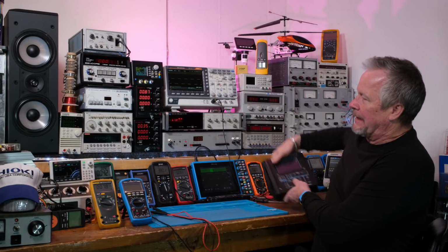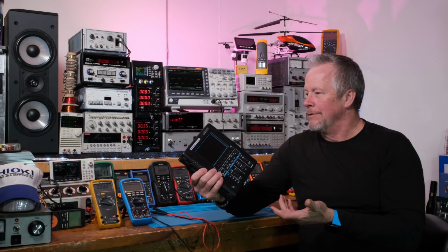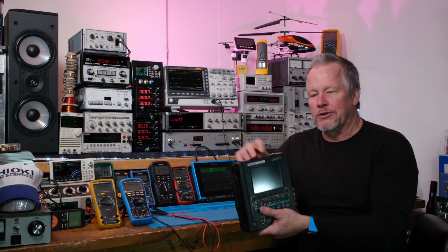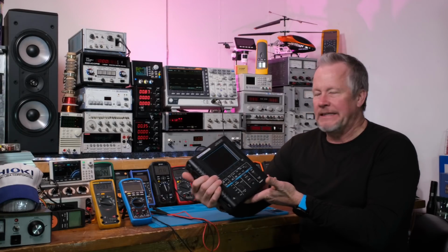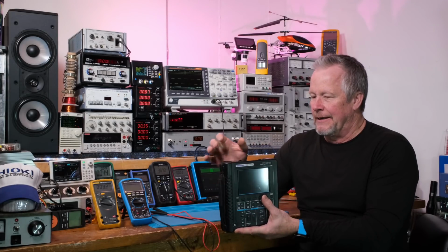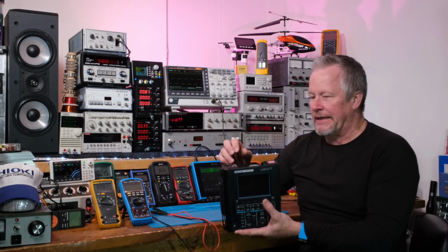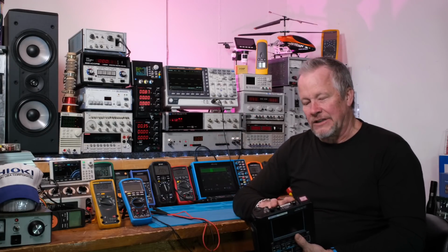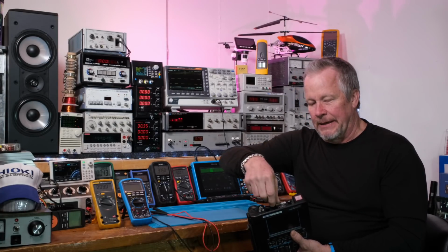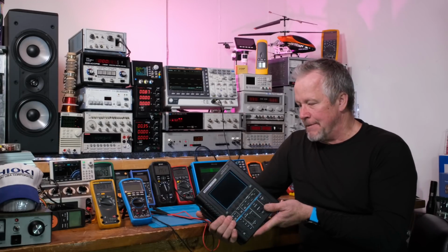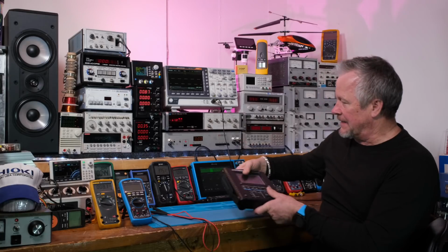And just understanding ground symbols. Like a product like this, portable product, battery operated. It's an oscilloscope I've had for a long time from Tektronix, THS 730. This is an awesome scope. Loved this scope back in the day. Today it has kind of a small screen, I guess. This mixed signal is pretty darn nice. One advantage this guy had, he only had 2 channels, but they were isolated from each other. So galvanic isolation. So that's another term, galvanic isolation.